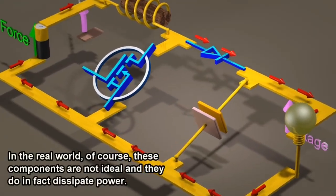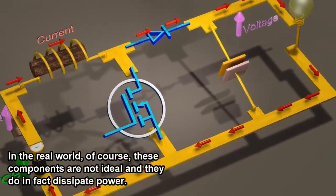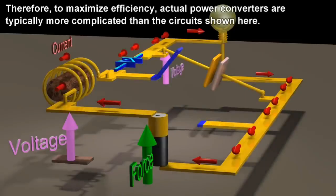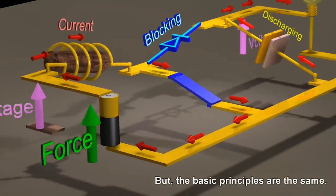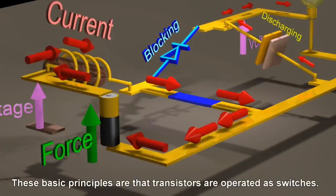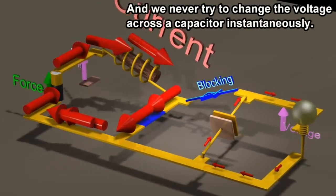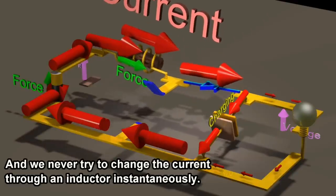In the real world, of course, these components are not ideal, and they do in fact dissipate power. But the basic principles are the same. These basic principles are that transistors are operated as switches. And we never try to change the current through an inductor instantaneously.